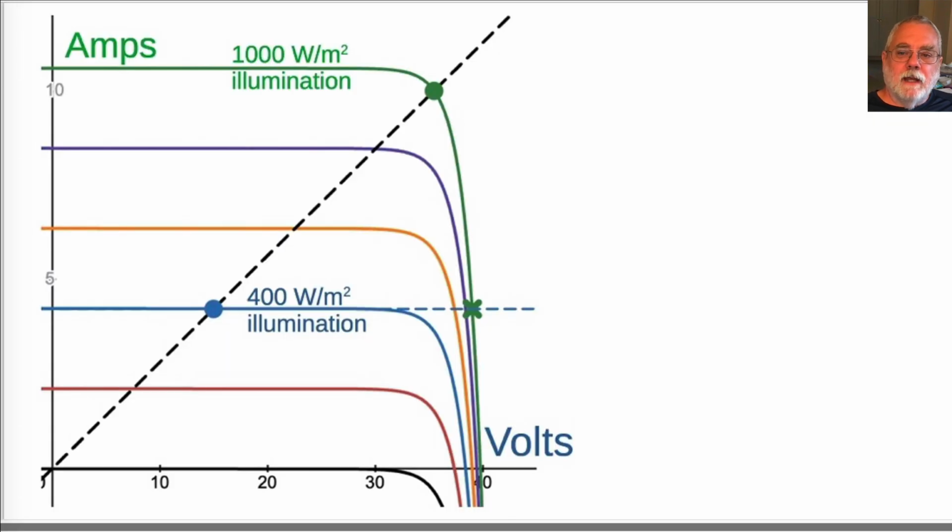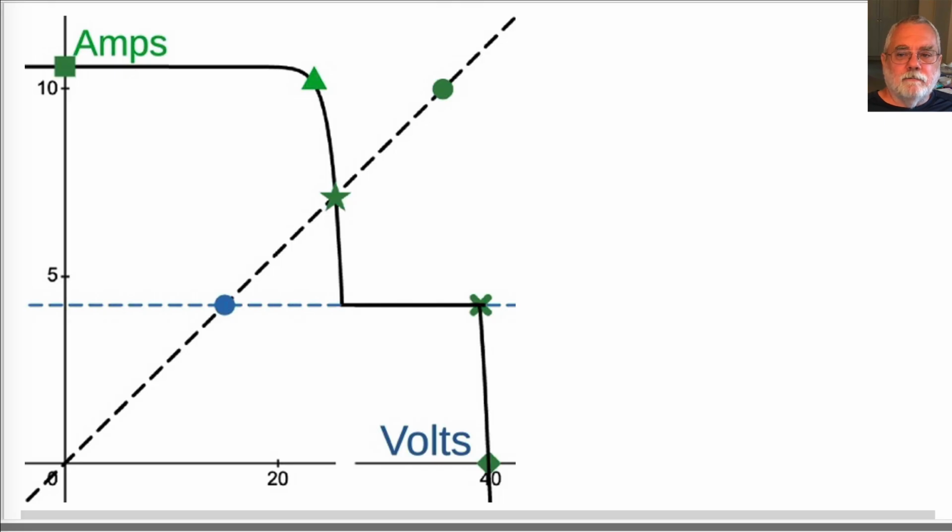If one panel is connected to a microinverter or DC power optimizer, the active control element will shift the operating point, attempting to maximize power extraction. Here is the approximate IV curve for 59 solar cells at full illumination and one solar cell at 40% illumination, 3 bypass diodes, and solar cell reverse breakdown voltage more than 13 volts. At least I think this is the IV curve. I confess I find this confusing to think about, and I could have made mistakes. Do you agree that this is the IV curve?